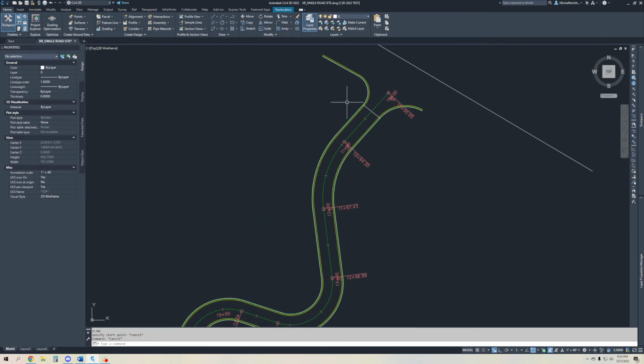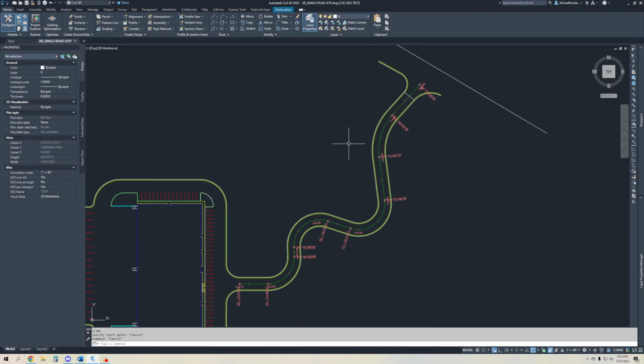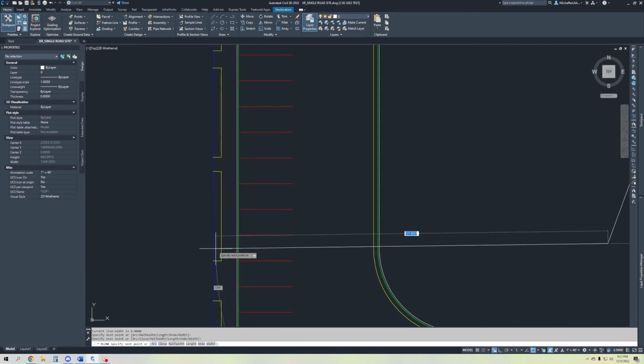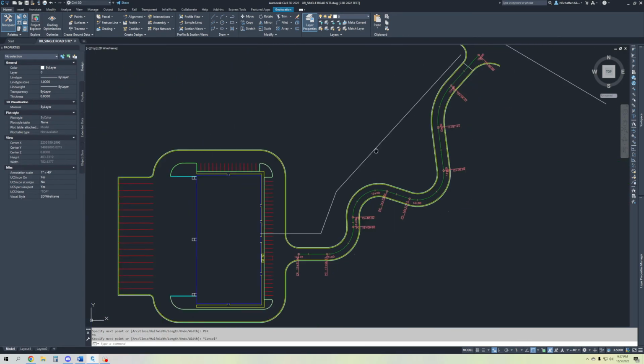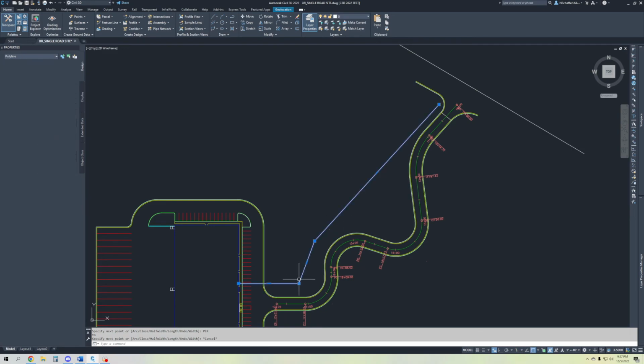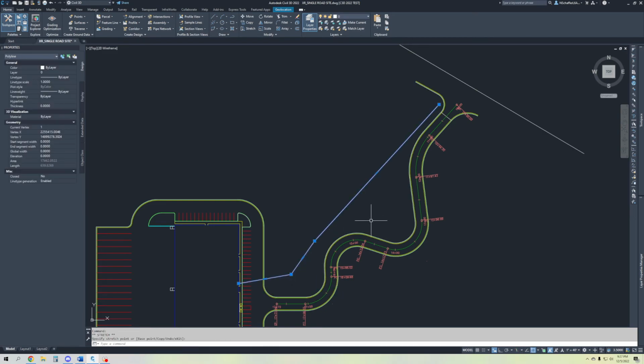So you can create another one that would be an alignment that looks maybe something like this, and you go along, and maybe you need it to curve so that your point of connection for the building is somewhere here. You can now create an alignment with this and have your water pipe follow that alignment so that you can get water to your building as you need.